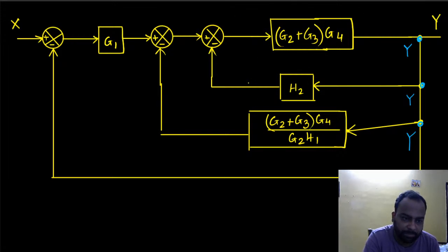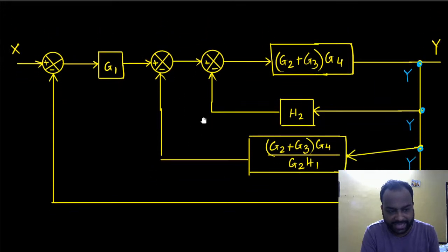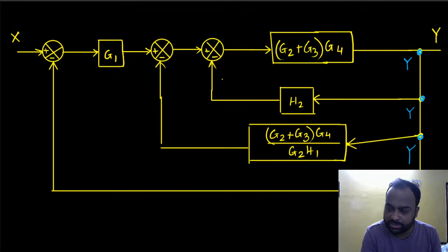Once you construct a simple feedback loop out of this, if you write down the equivalent transfer function out of this, then consider another feedback loop out of this. So basically what you have to do next is to construct a feedback loop, simplify this, and after writing down the equivalent transfer function, you would have another feedback loop, do that, and then you have the cascade block, do that, then you have another feedback loop, right?